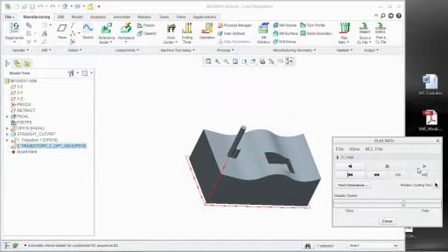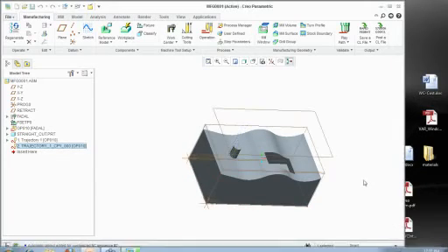All of the other toolpaths have a little bit different of an interface that pops up, and that's why I use the Process Manager. In the Process Manager, you can do quick copy and paste, and duplicate toolpaths quickly over and over again, if essentially they're the same thing with just a few changes from one to the next. Okay? All right. So that's copy and paste.